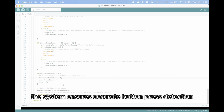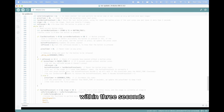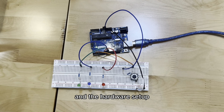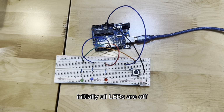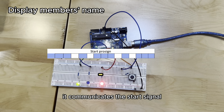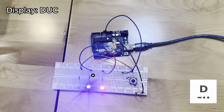The system ensures accurate button press detection using debounce delays and a timer to reset if the button isn't pressed again within 3 seconds. Regarding the overview of the project and the hardware setup, our system consists of 3 main stages. Initially, all LEDs are off. After pressing the button twice, consecutively, it communicates the start signal, the names of the team members, and the stop signal, all in Morse code.